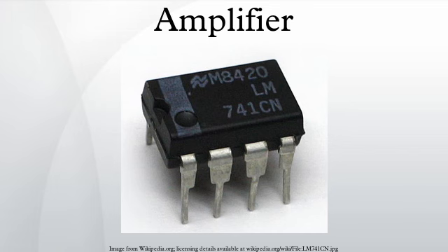The residual distortion is dependent upon the bandwidth of the tuned load, with the center frequency seeing very little distortion, but greater attenuation the farther from the tuned frequency that the signal gets. The tuned circuit resonates at one frequency, the fixed carrier frequency, and so the unwanted frequencies are suppressed, and the wanted full signal is extracted by the tuned load.